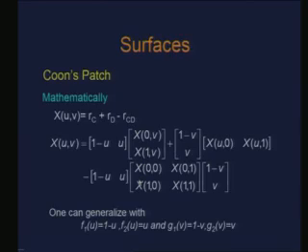Ruled surfaces are the simplest form of surfaces for obtaining a surface interpolating 2 boundary curves, right, and Coons patches are the surfaces for obtaining the surfaces for 4 boundary curves, right. And we can see that they can be represented in a very similar way as what we observed in the case of parametric curves,